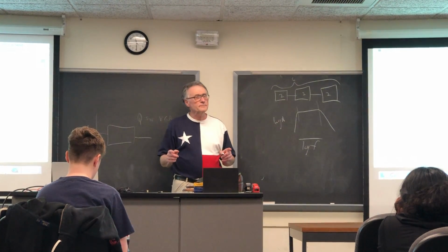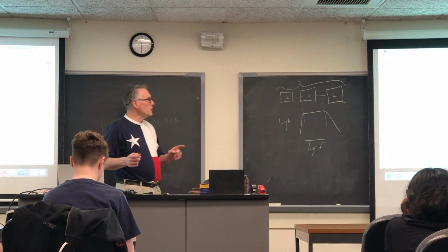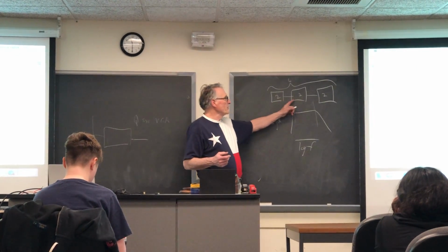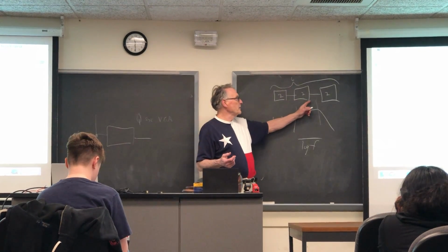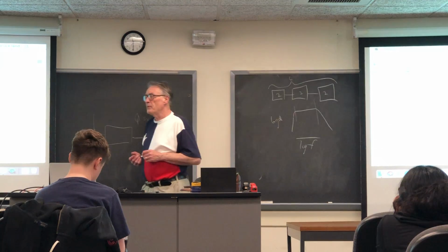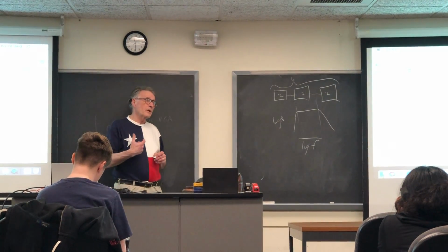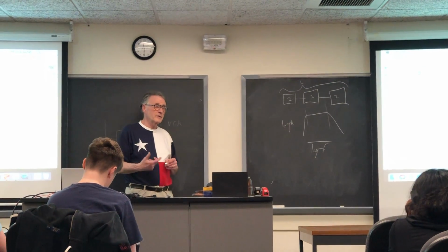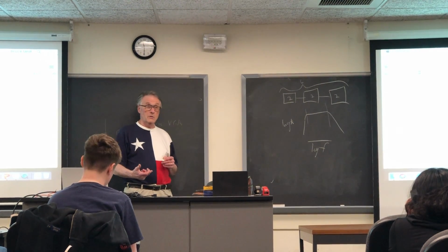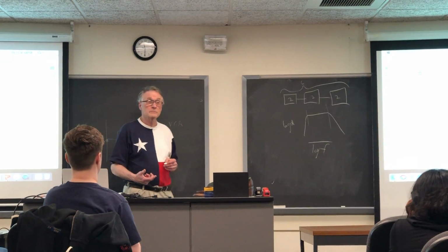The answer is yes. So you can show that by factoring a 6-pole filter or an 8-pole filter into 3 terms or 4 terms, that you can reduce the number of bits required from something like 32 to something like 10. That's huge in terms of multipliers.